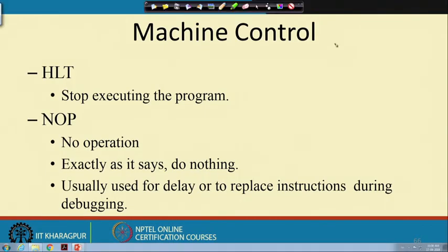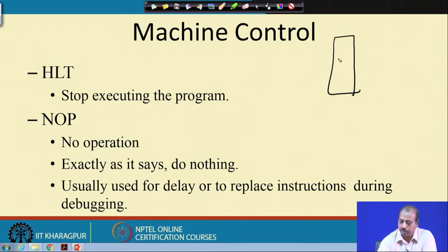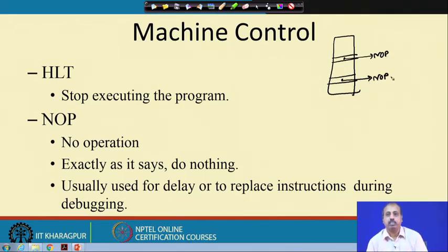After the debugging is over, these instructions, which are basically some sort of interrupt, are modified to NOP, so that in the final version there is no debugging instruction included. We can very easily modify these debugging instructions to NOP instructions without hampering the code which is otherwise generated. All the addresses remain unchanged, and only these parts are modified to NOP.